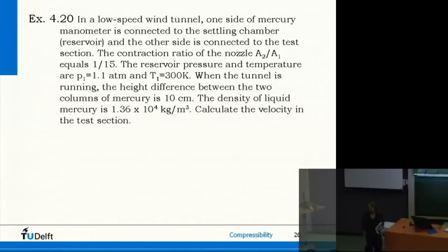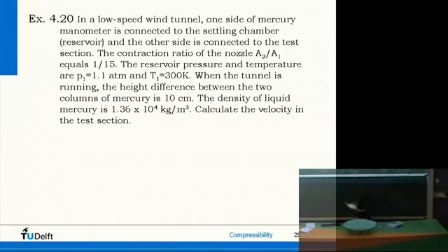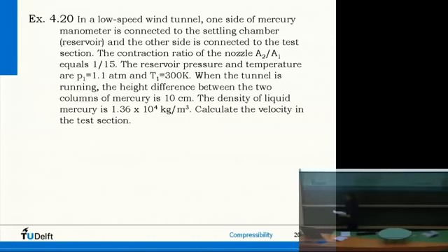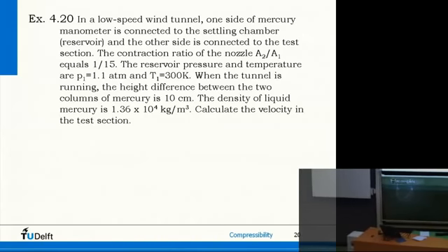So question 1 is, what does a manometer do? I hope you'll remember from high school, but if not, I'll repeat it. So let's first start with a manometer, which is a way to measure pressures. A manometer is a U-like tube. We connect the sides through tubes to certain locations in the wind tunnel. One is the settling chamber and the other side is the test section.